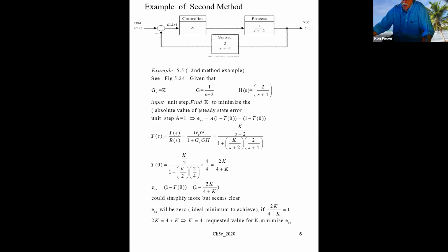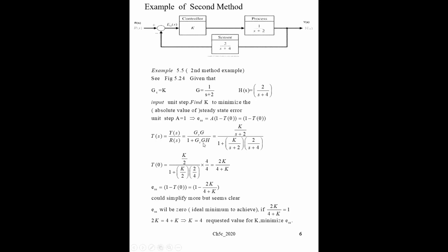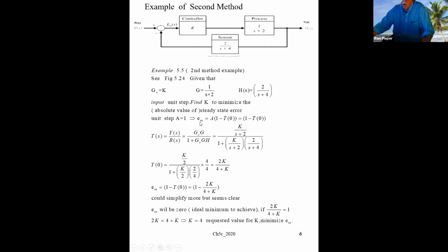All right, so I trust that since this has practically come up from the very start of the class, the so-called canonical form recipe for transfer functions, you could see the GC and the G. Here, this is the GC, it would be the G, and there's the H. So that would be the correct canonical form recipe. The plus there is because of the minus there, just to remind you. And then we plug in. We're going to set s equal to 0, but it could be simplified if you wanted to, but it doesn't have to be.